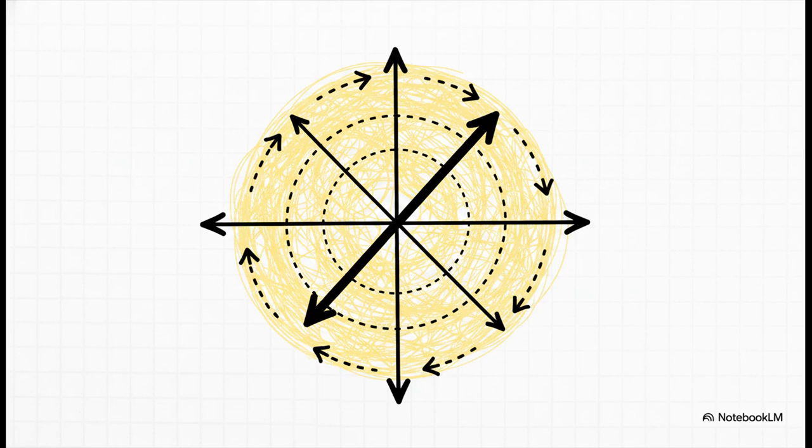Visualize this in your head right now. As the frequency sweeps upward, imagine a vector anchored right at the origin. As that frequency increases, this vector rotates, usually clockwise, and actually changes length, tracing out this completely unique trajectory. That trajectory is quite literally a fingerprint of your physical system's behavior.